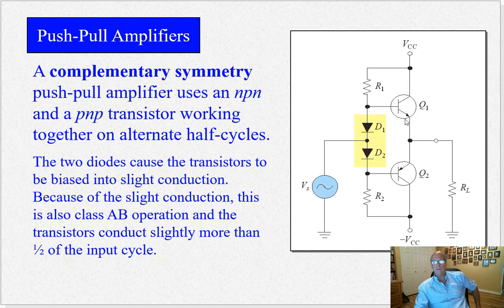And this down here just talks about what I was talking about. Each transistor, again, conducts for half the input cycle. When there is no signal, these transistors are shut off, so they're not dissipating any power. So that's good.